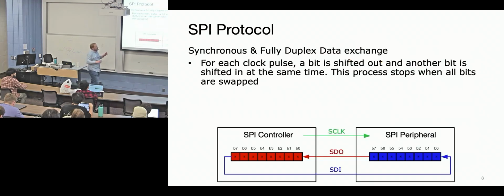The most primitive way to think about SPI controllers is as a bunch of shift registers linked together. You say, okay, go, and then you sequentially clock data out, and that sequentially clocks data back in. So in this sense, it's fully duplex. You have data in one and data in the other, and they just transpose each other, going from one device to the other. Typically that's not necessarily how it happens, although this is what the underlying structures look like.